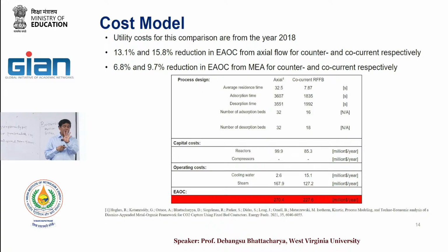So you multiply by that, and this is the volume, which you multiply by 1 minus epsilon, the bed voidage. That gives you the solid, and then you multiply that by the density of the solid, the bulk density, and that will give you the mass.